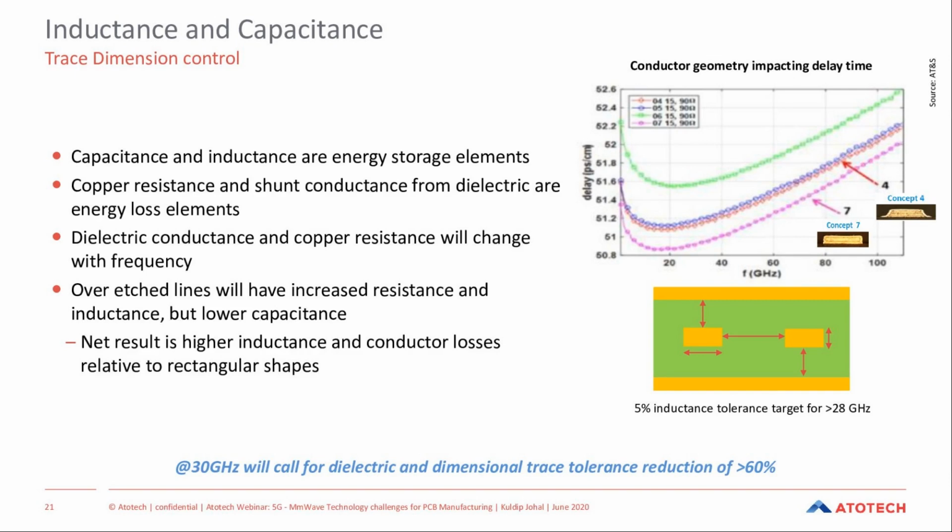So that's true. And if we take, say, a print and etch type of circuit product, we will see that we will end up with a trapezoid type of pattern. And this basically then changes the area of the top, the bottom, the sides, etc.